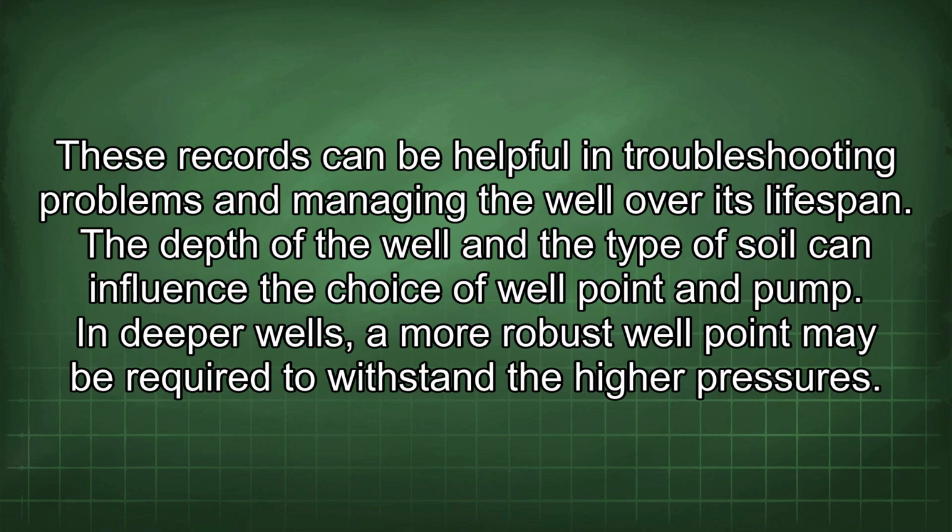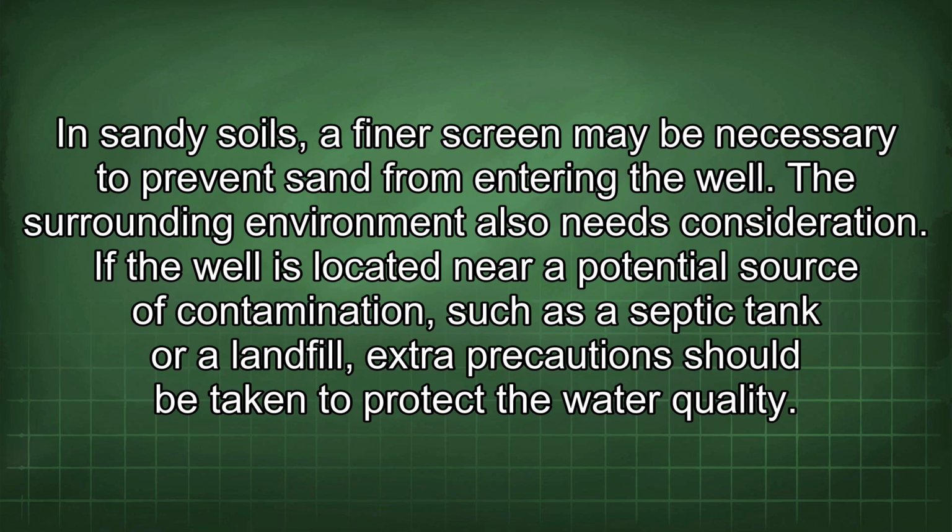The depth of the well and the type of soil can influence the choice of well point and pump. In deeper wells, a more robust well point may be required to withstand the higher pressures. In sandy soils, a finer screen may be necessary to prevent sand from entering the well.